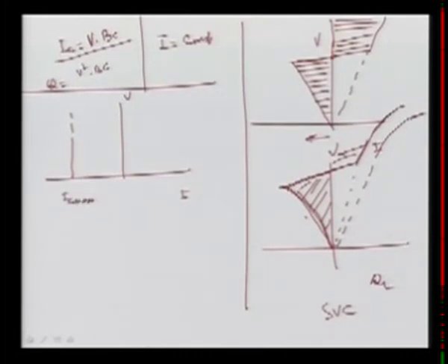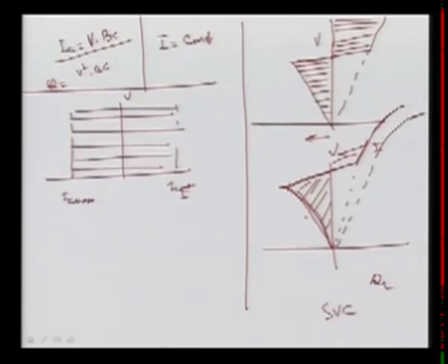We can go up to that maximum, meaning we can vary current on both sides, and we can go here up to your IL max value. So this is your operating zone in between. But again, as I said, if the voltage is less, we have to operate in this capacitive zone. Here this is the capacitive, this is your inductive.